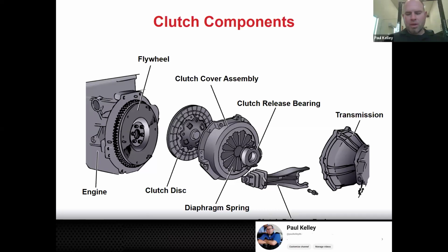If you've worn your brake pads out and the friction lining has been worn down year after year, miles after miles, you've probably caused some issues on the rotor. So this is the equivalent of the rotor, but this is only one side of the surface. The other side is actually in the clutch cover, which a lot of times we'll call the pressure plate, right? So there are two surfaces there we're very concerned about when we do clutch work.